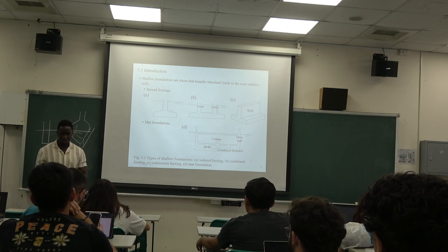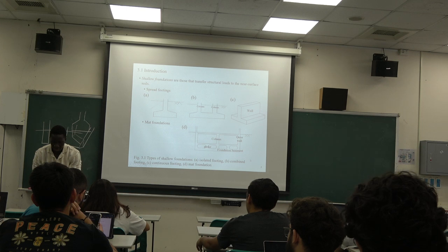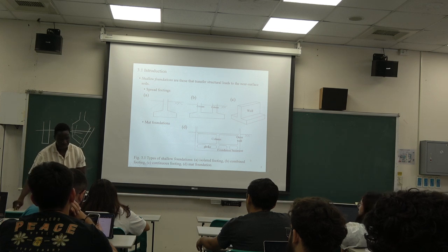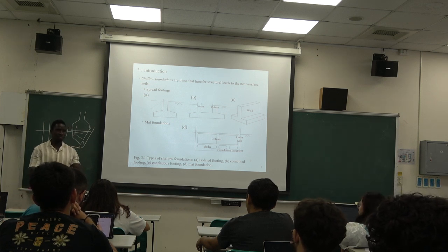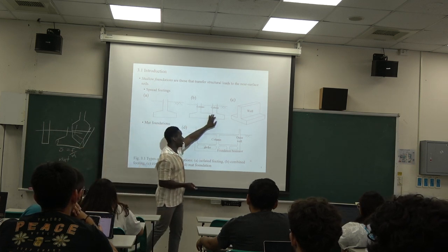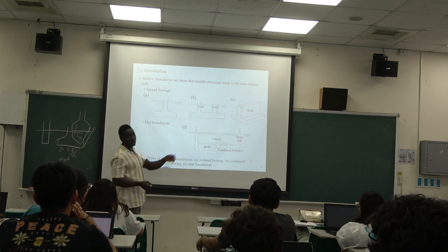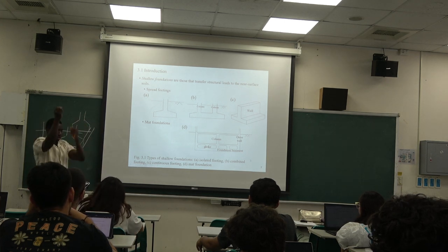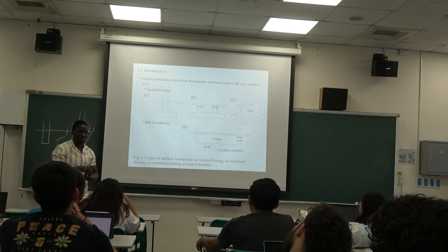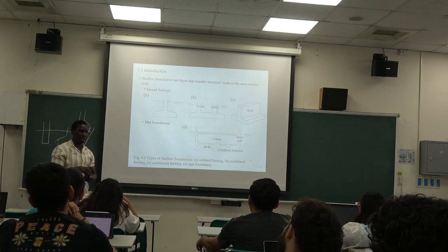Okay, so it's just like my piece of land that I want to build on, then I just spread a mat onto it. So that means the whole surface area here is my foundation. Instead of just having this spread footing or this, this one also depends on specific conditions, because before you design the foundation, you need to know how much loading the foundation needs to take, right? Or what type of structure am I building?